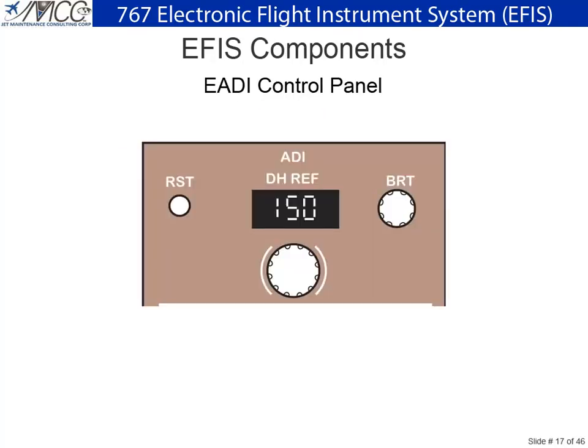The EADI controls and their functions are as follows. The EADI display brightness control is a rotary knob used for adjusting the EADI brightness. The decision height set control is a 2-speed 10-turn rotary switch used to select the decision height. If the control is turned slowly, the display will advance 1 foot per click at 24 feet per revolution. If the control is turned quickly, the display will advance 4 feet per click at 96 feet per revolution.